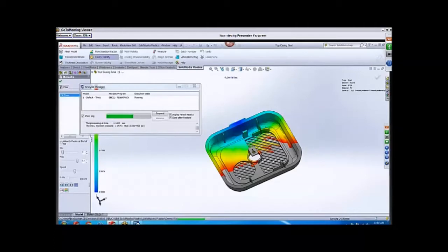What you'll see is that we have two flow fields coming together, and that's going to create something called a weld line. This phenomenon is caused by something called the racetrack effect, where plastic rushes in from one side much faster than the other side. As a result, we get these weld lines at these locations. Weld lines are really not ideal because you can see them in plastic parts, and with a plastic part, you want it to look pretty. You don't want to see those weld lines.